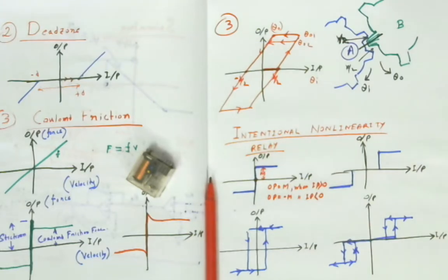However, if you go close to 4.5 or 4.9, close to 5 volt, then it will be energized. It doesn't mean that a 5 volt relay requires exactly 5 volt supply. It may be energized with 4.5 volt or 4.2 volt, but it requires a specific amount of voltage to be energized.